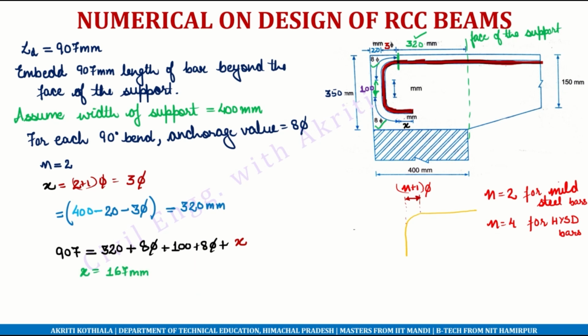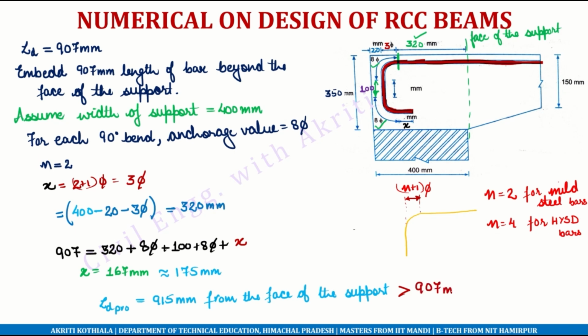167 mm. However, we can just increase it slightly to 175 mm, and thus the total value which we have provided, LD, will be equal to 915 mm from the face of the support. Since we have provided this value greater than the required 907 mm, hence we are safe and this is okay.